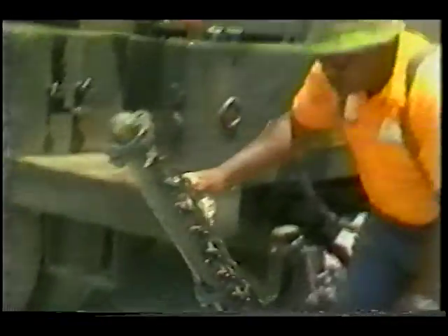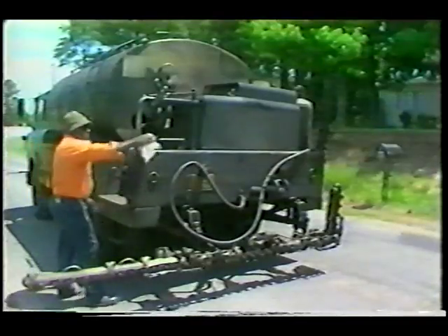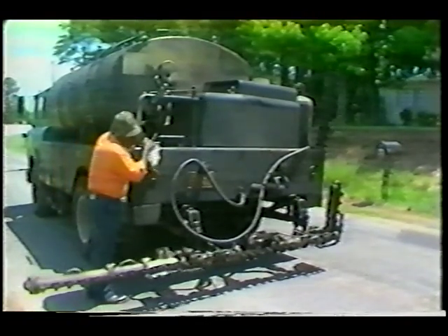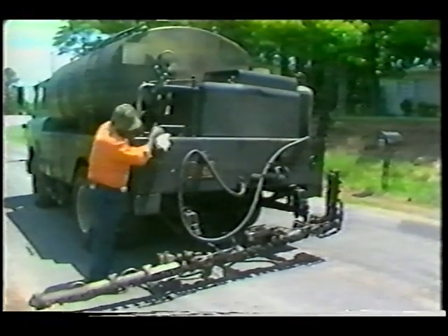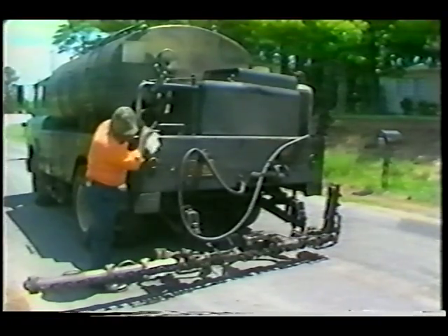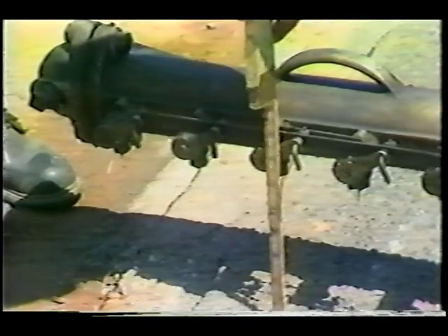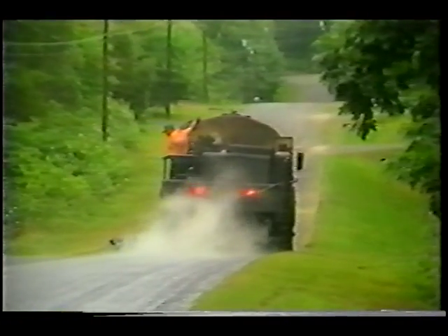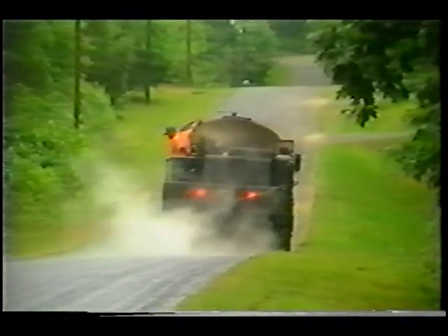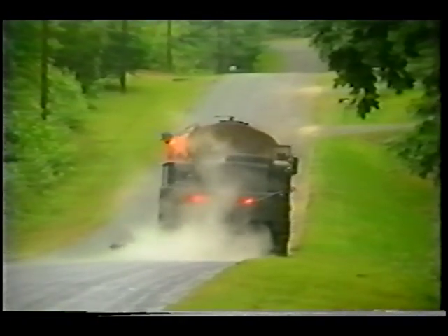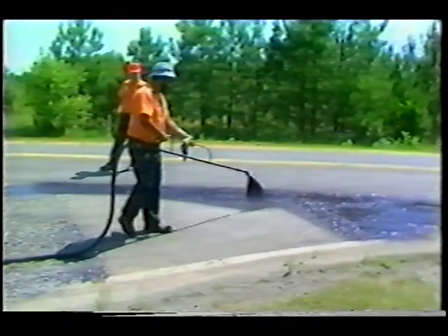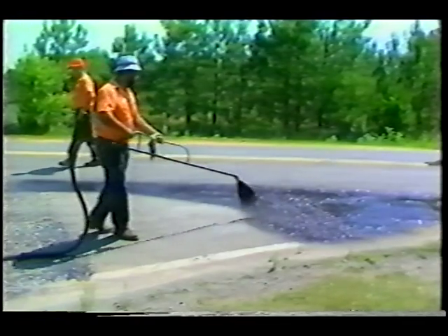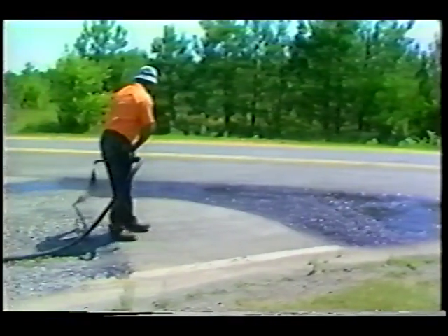The width of application is varied by cutting off portions of the spray bar. Follow the manufacturer's instructions for specific distributors for adjusting spray bar height and nozzle settings so that the desired application rate and coverage is achieved. The distributor uniformly applies asphalt to a surface at a specified rate, regardless of changes in grade or direction of movement. A hand spray attachment is convenient for applying asphalt in areas that are hard to reach with the spray bar.